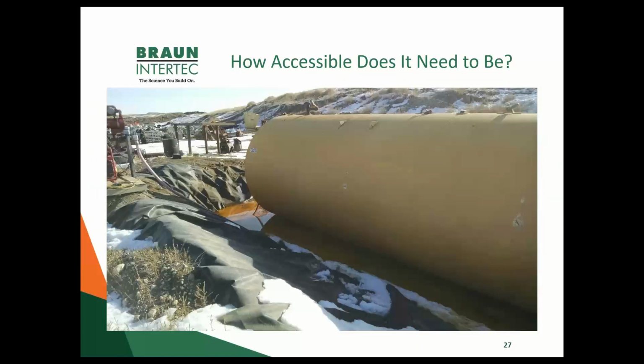Here's kind of a splitting the difference with a liner system and earthen berm. Again, it doesn't look very pretty, but it does the job. If you're only on site for a couple months, maybe this is the option to go with. But if you're going to be on site for years, you'll get tired of walking over this berm every time you have to get to that tank, so maybe you want to look at a different option.